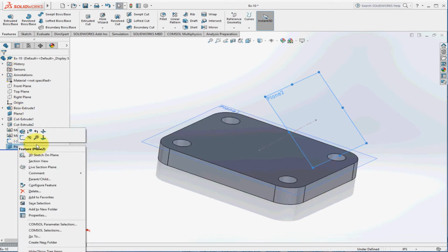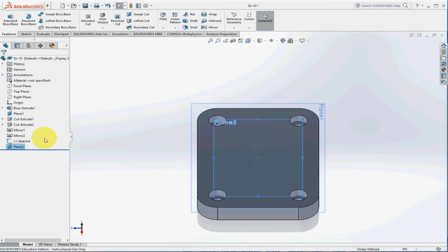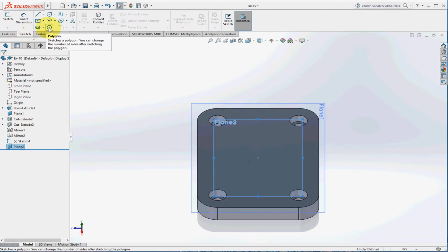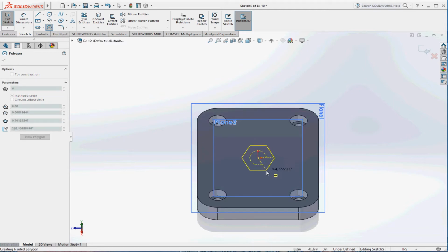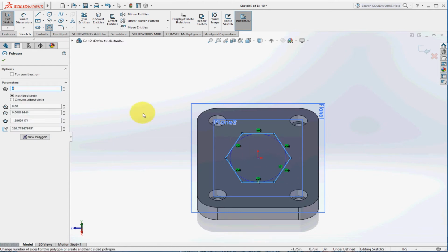And so I've selected that new plane, and now I'm working straight down from that plane, and I need to now go ahead and make a hexagon here. So you have to be kind of deliberate when you do this. You're looking at your drawing, at the radius, or which the flat side is, and it's parallel to the piece itself. And so we're using a circumscribed circle, and I'm just putting all the coordinates in here. So the circle diameter is 1.5 inches.